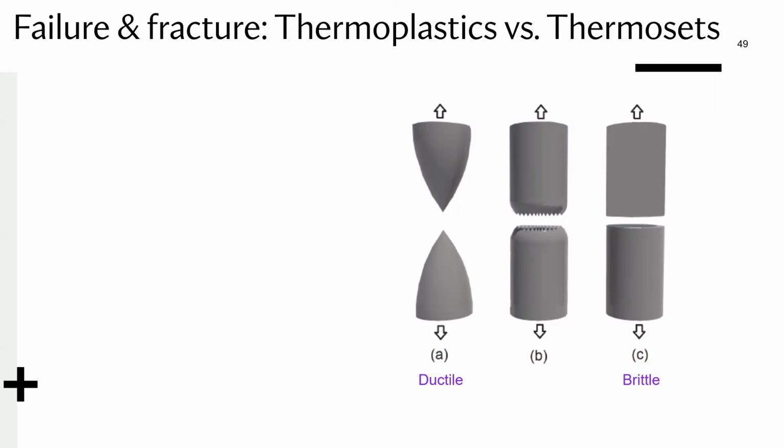In contrast, ductile failure is the case where you actually have this necking, and you can see it kind of in these 3D renderings, that the material has sort of gone through this necking process, and the intersection at which the failure has happened is reduced quite significantly. And so it's as if you were stretching chewing gum or another sort of rather elasticy material until it failed. And this is basically the two extremes, brittle and ductile, but there's also a case where it's sort of an in-between situation.